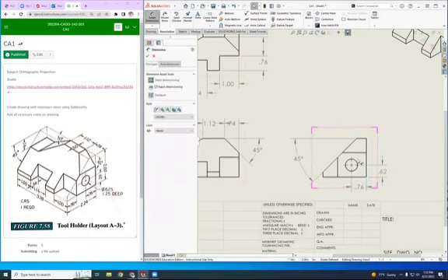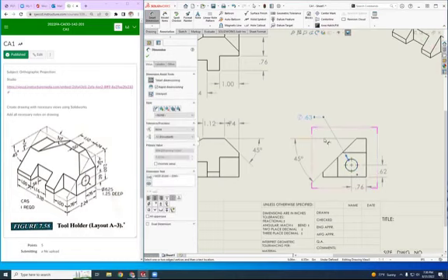I am also missing the dimension callout, this one here, the size of the hole. So notice that it's a 0.625, so 3 decimal places in the tolerance position. And then it also has an extra note. It says 1.25 deep. We have to manipulate the dimension text by placing your cursor there, pressing enter, and typing in 1.25 deep.